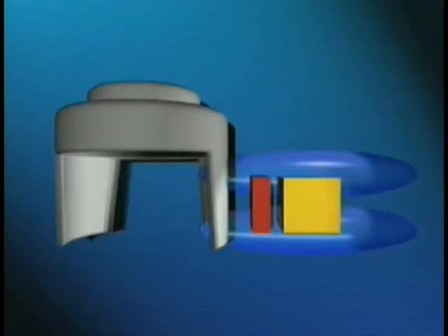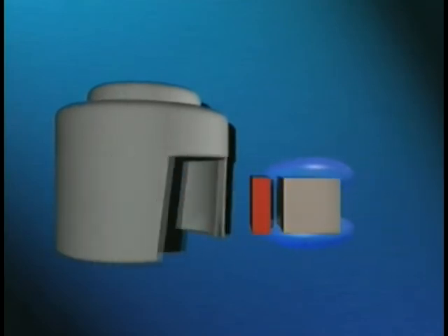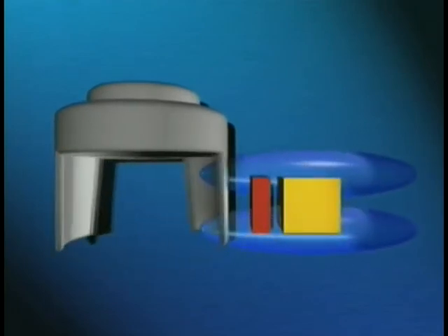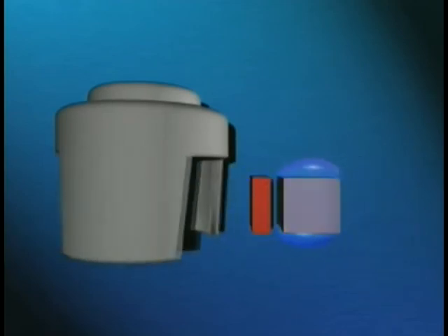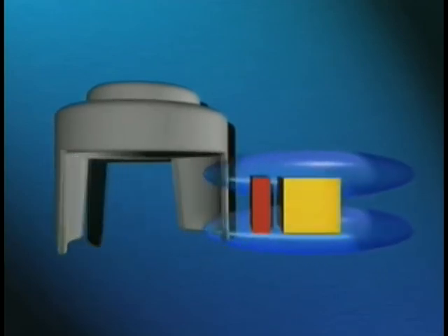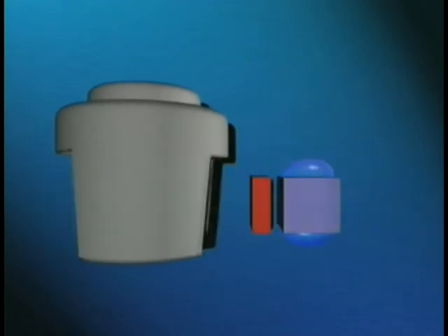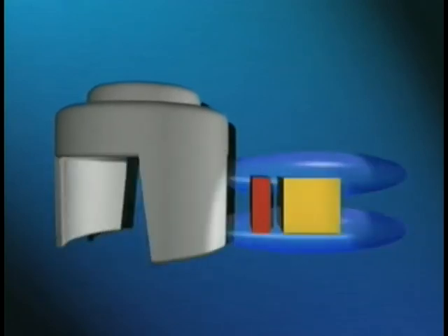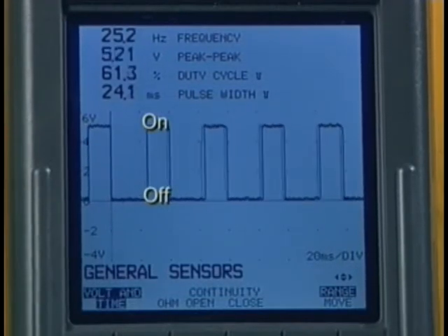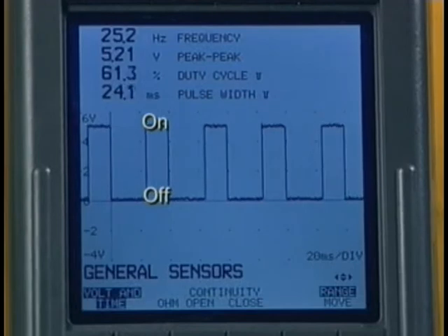When the shutter allows the magnetic field to reach the Hall layer, the magnetic field expands and the switch generates a very low voltage. When a moving metal shutter plate attracts the magnetic field away from the Hall layer, the Hall effect switch produces a voltage signal. The Hall effect circuit uses an amplifier and inverter to change the signal that is sent to the control module. The inverter changes the low signals to high and the high signals to low.